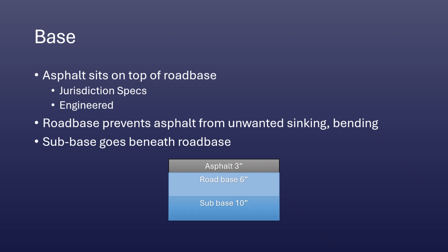And so if you're in an area where the underlying soils are just super collapsible, maybe there's high plasticity, high elasticity in other areas, maybe there's a lot of water that you're dealing with, you'll probably see some sort of subbase to protect your asphalt from getting potholes, from getting cracks, things like that. What's interesting to note is that when asphalt does fail, it's usually conditioned from underneath instead of on top.